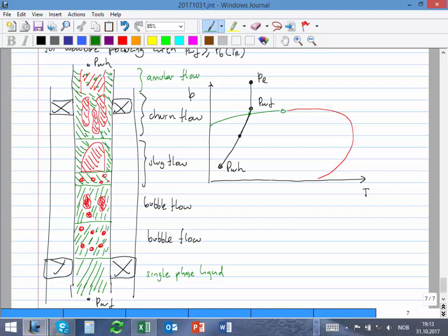I guarantee you. You say, why so much change? It's not out of the mind. You can have the whole change in different flow patterns along a well, and that causes different problems because I have to calculate pressure drop. So I cannot make the assumption that all sections are the same. I have to subdivide, calculate what flow pattern I have at every point, and then make an estimation of the pressure drop. And that creates a lot of trouble just because of what we are looking at.